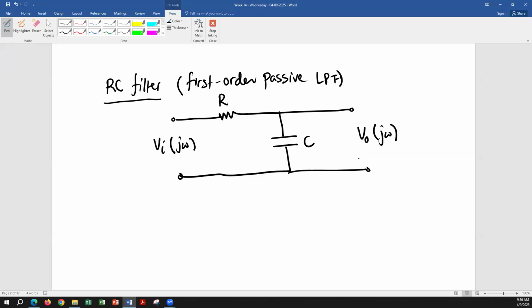Voltage divider is how you're going to find the output. That's a different story, right? But if I give you a circuit and I say, identify if it's a low pass filter, high pass filter, whatever, to identify that circuit, you're going to start thinking about how the reactance is changing when you're changing the frequency. So tell me how the reactance of the capacitor is going to change when I change the frequency of the input, starting from 0 all the way up to infinity.